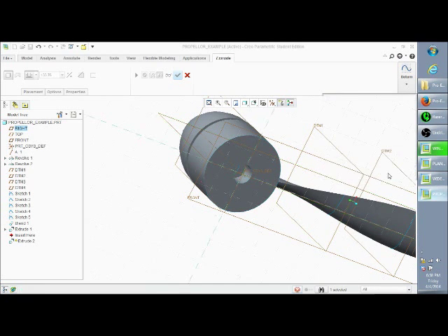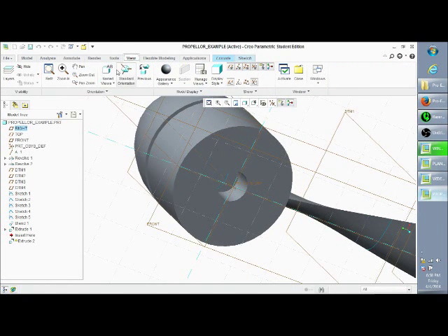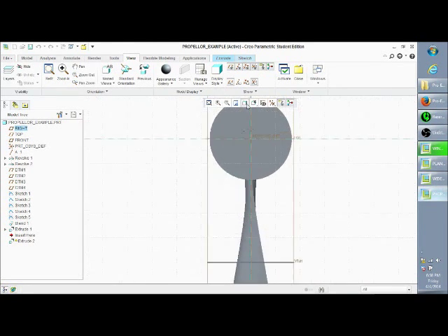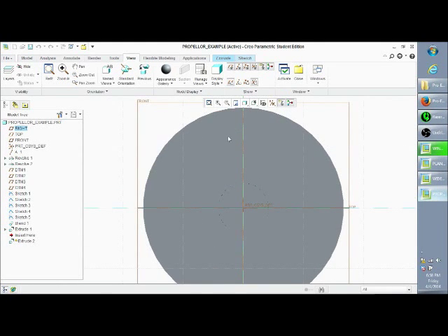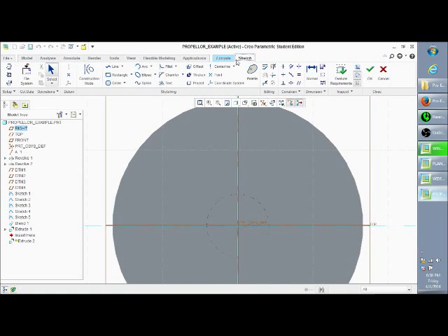So we can go ahead and click Sketch. It doesn't matter where necessarily you start, as long as you start with a flat shape on one of these axes. So what I'm going to do is create a center line. When I was using the revolve tool, your center line was located right here.